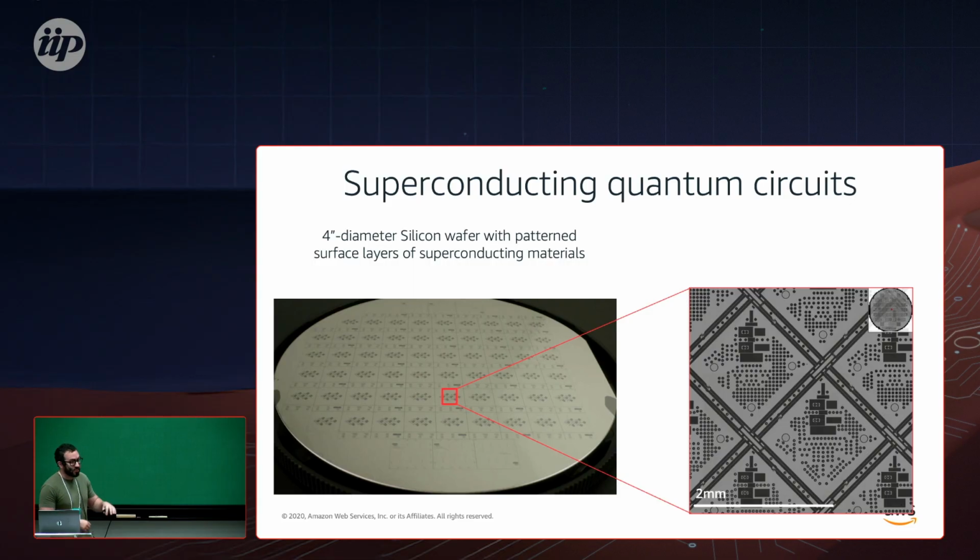Whereas here, there are all kinds of problems, right? There are two-level system defects, right? There is imperfection in the Josephson junction size, which leads to imperfection in frequency and so on. So there are a lot of fab challenges that one has to address. But that's the game we're playing, right? Just trying to make fab reliable enough that we can build good enough circuits. And then maybe if we can do it, we can scale more easily, because of course there's a whole industry that's just about scaling microchips.